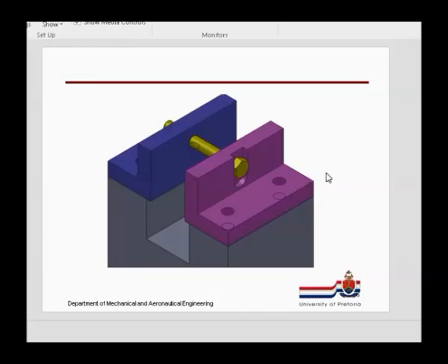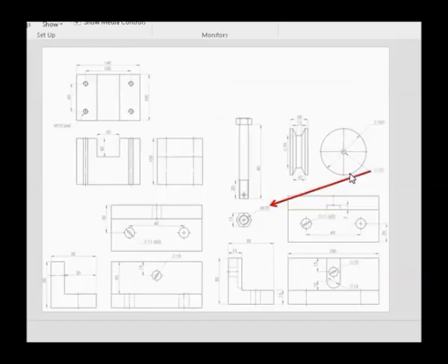Now what this groove will do is it would actually act like a mechanism to stop the bolt from rotating. So putting the bolt through that hole means the wheel or whatever we put on the inside is not able to turn this bolt, which is very beneficial, because if we put a nut on the other side, it means that it can never undo the nut by itself.